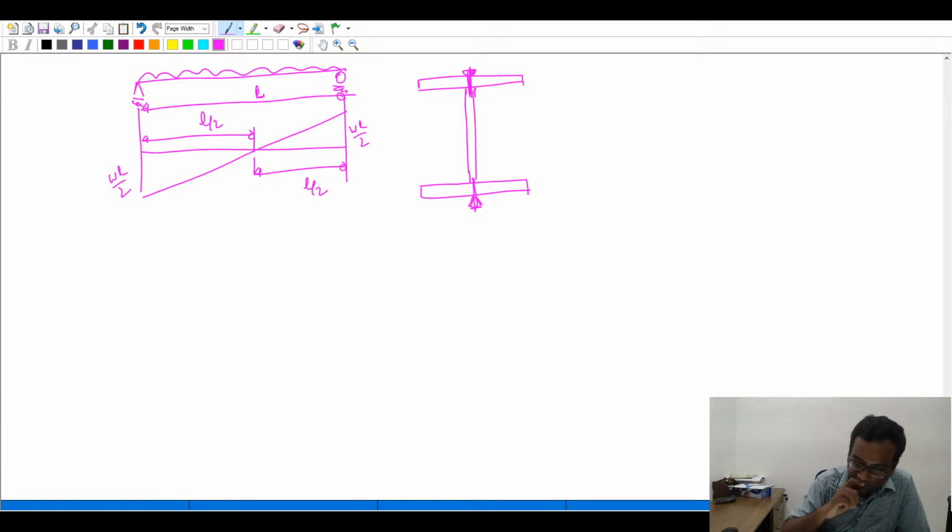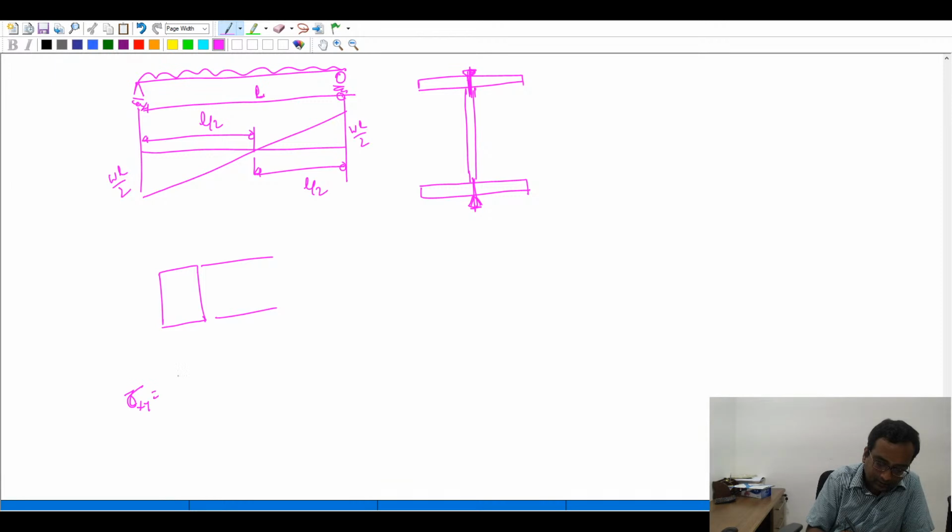Is the question. You know that if it is a rectangular beam with uniform thickness throughout the cross section, from the expression tau xy is equal to VQ by Ib, you can construct the variation of the shear stress along the depth, which will be a parabolic variation, the maximum occurring at the neutral axis.